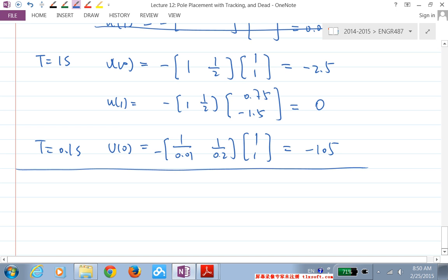I think it's probably easier for you to answer because it's a continuous system. Then you can look at the tables or diagrams. You see, the poles out here, the response is supposed to be like this, and the poles here are supposed to respond like this. Remember the two formulas that I gave you in the first lecture, which basically relate the damping ratio and natural frequency to certain design specifications, such as sampling time and percentage overshoot.